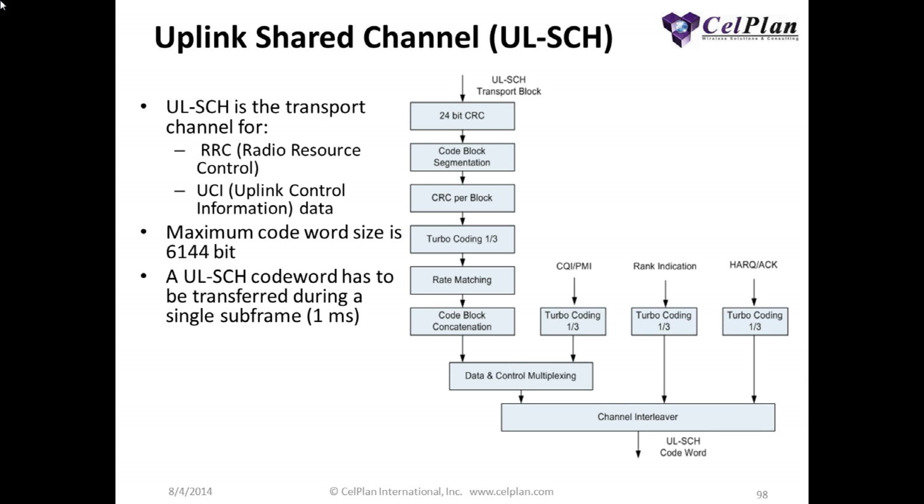Basically, a transport block, and the transport block in the uplink is very similar to the transport block in the downlink. So this transport block receives a 24-bit CRC.